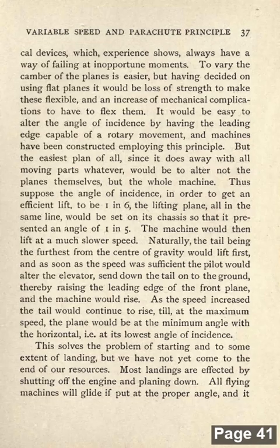As the speed increased, the tail would continue to rise, till at maximum speed the plane would be at the minimum angle with the horizontal, i.e. at its lowest angle of incidence. This solves the problem of starting, and to some extent of landing. But we have not yet come to the end of resources.